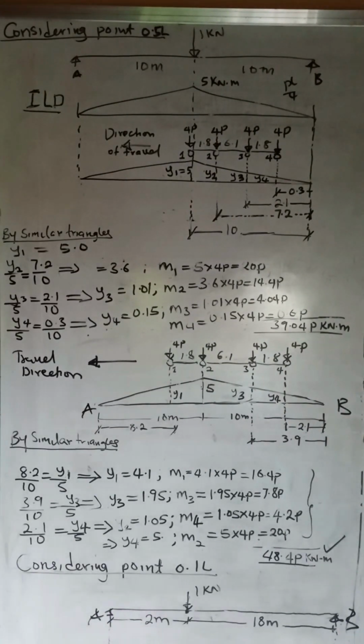All right. Now, the next step we're going to take is application of the loads. The load we are going to be considering is an HB load from the BS 5400 and BD 37/01 code, British standard codes. Now, the vehicle, like we know, is made up of 4 axles. Each axle comprises 4 wheels. And let's call the load on each wheel P. So we're having 4P in each axle.